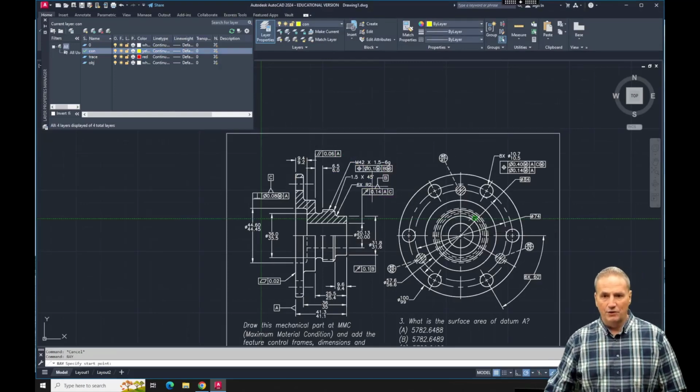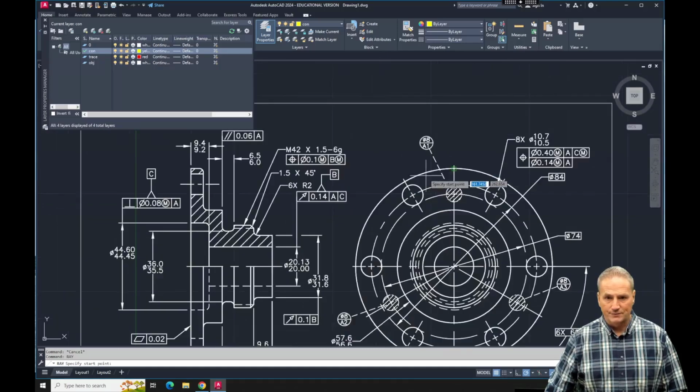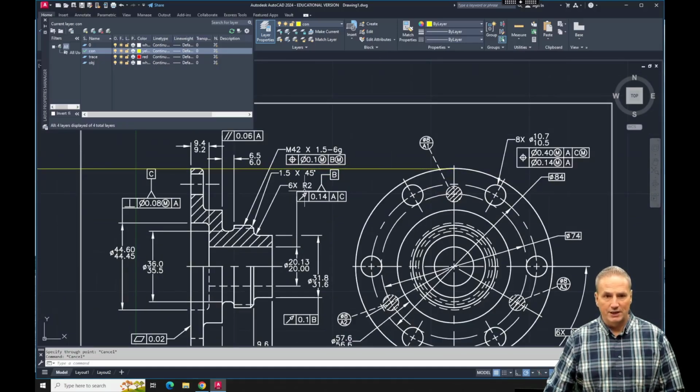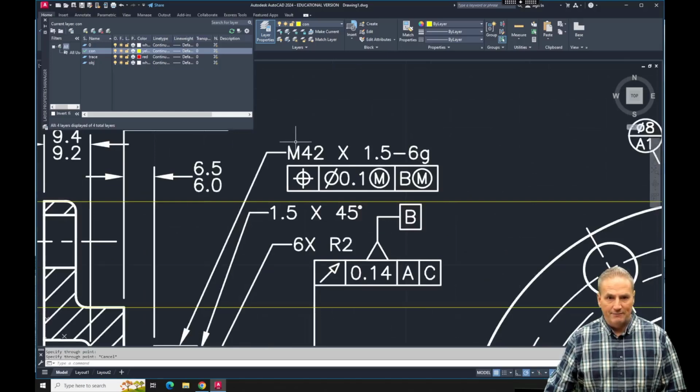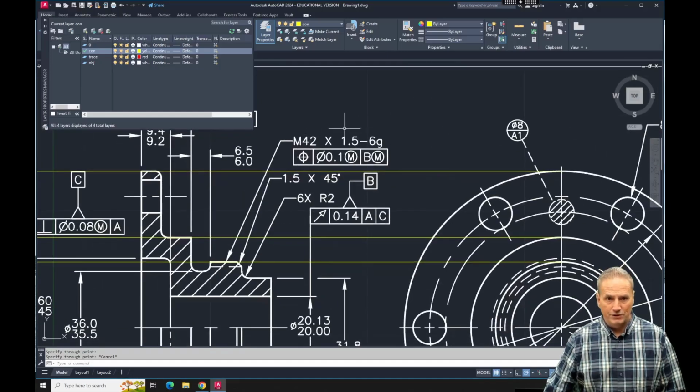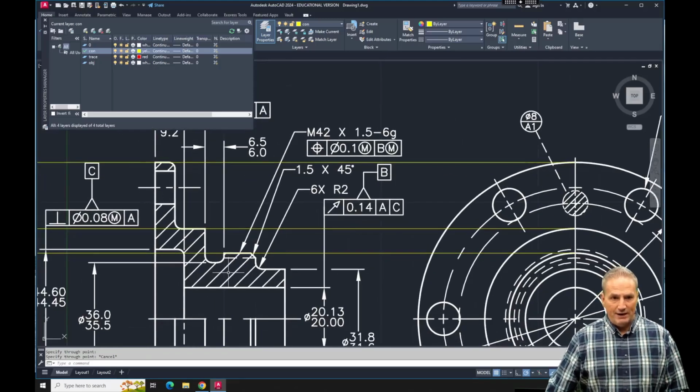All right. So what I'm going to do eventually is draw the right side. So I'll draw my circles, and then right from there I'm going to draw my construction lines over. Right? You can kind of see I want to draw construction lines that go through these major diameters. Right now I'm just hitting on the actual object lines, right? So we've got an object line here. This one is that M42, so it's a diameter of 42. There's a metric thread designation. All right, so I can have that one.